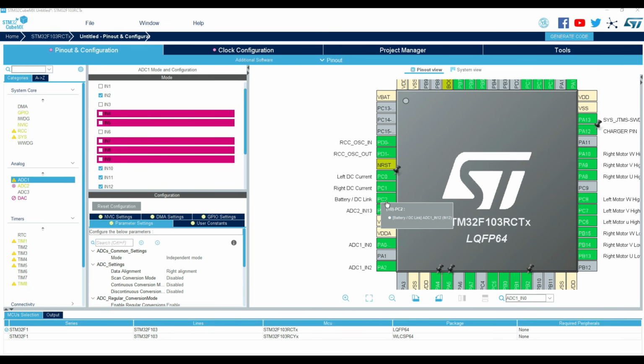It measures the DC link voltage, the battery voltage, the DC bus voltage, the main supply voltage that powers the inverter and motor. It is used for overvoltage protection, undervoltage warning, and FOC feed forward speed calculation.